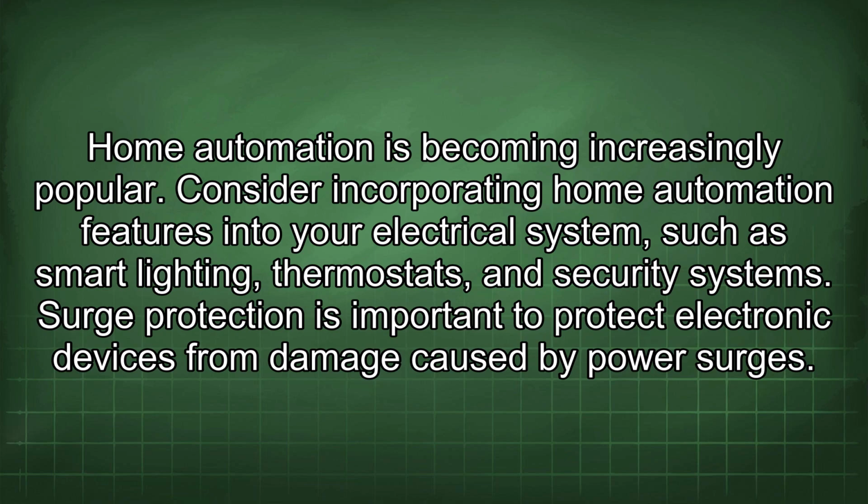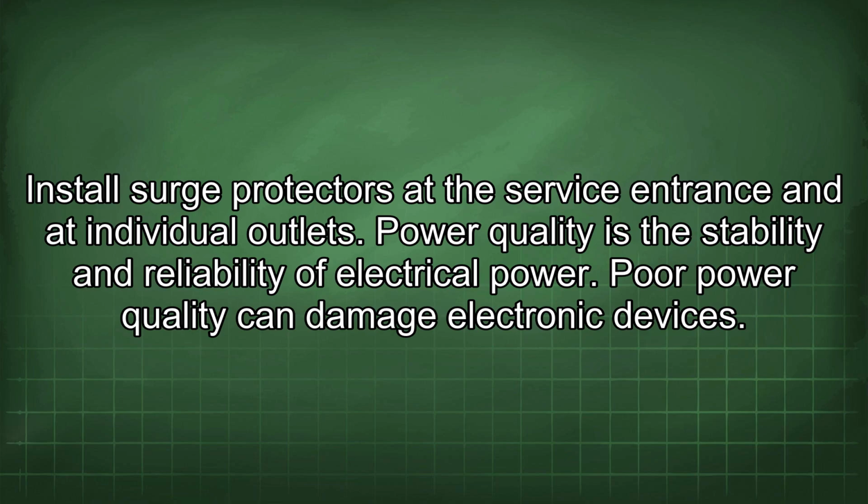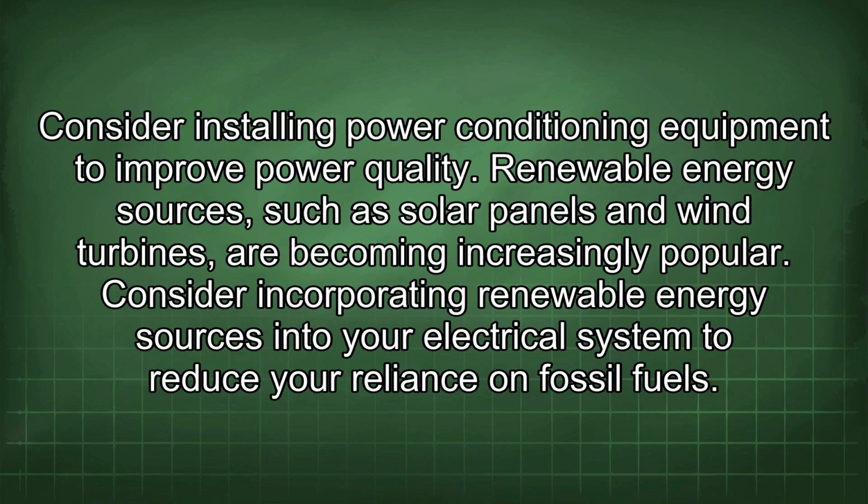Surge protection is important to protect electronic devices from damage caused by power surges. Install surge protectors at the service entrance and at individual outlets. Power quality is the stability and reliability of electrical power. Poor power quality can damage electronic devices. Consider installing power conditioning equipment to improve power quality.